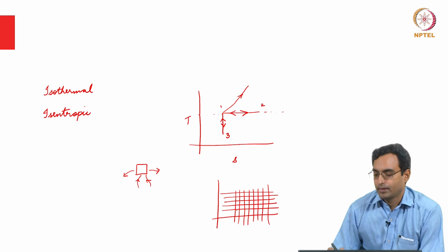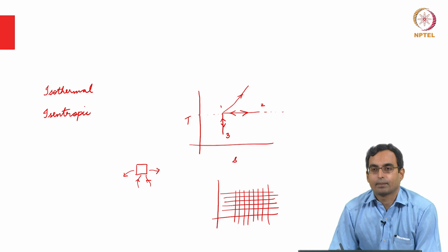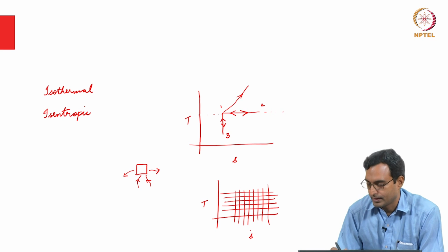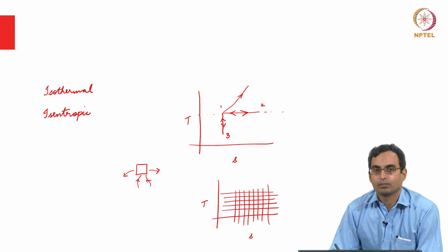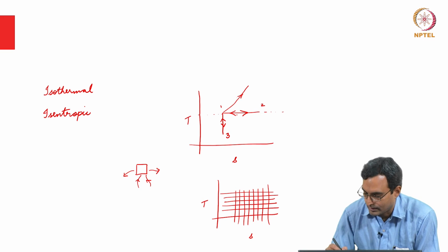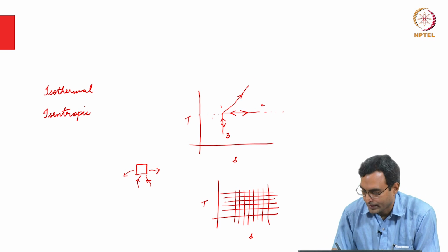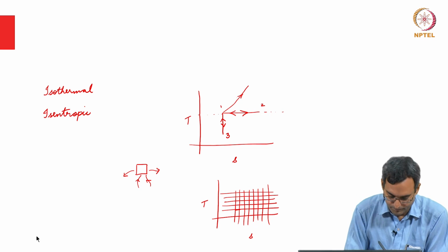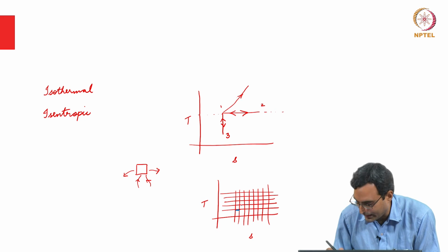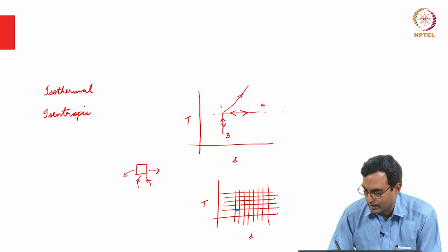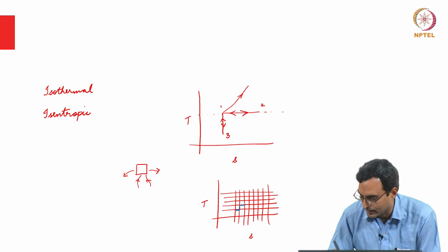In principle, we can think of these curves being extremely close apart, so that any heat transfer is very small, or any difference between 2 points is so small that everything is reversible. So, if I want, for example, an isobar of this kind, I can think of it as a combination of maybe going in this fashion. So, let us say I have isothermal heat transfer and then I have an adiabatic reversible process, then I again have isothermal heat transfer and then an adiabatic process and so on.